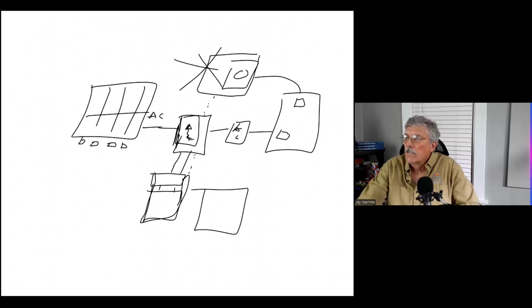So the panels are still going to work, the battery's still going to work, but you no longer have any possibility of backfeeding to the grid. Then as soon as the grid is reestablished, it's going to reconnect, and you're going to go into grid-tied mode. So you might have power that comes in to recharge your batteries, for example. It really depends on how you set them up. So these become very proprietary.